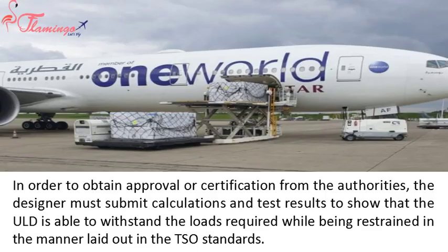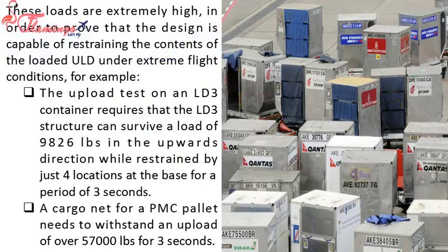In order to obtain approval or certification from the authorities, the designer must submit calculations and test results to show that the ULD is able to withstand the loads required while being restrained in the manner laid out in the TSO standards. These loads are extremely high, in order to prove that the design is capable of restraining the contents of the loaded ULD under extreme flight conditions.